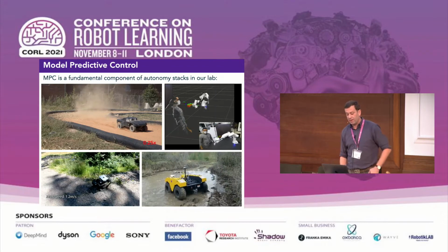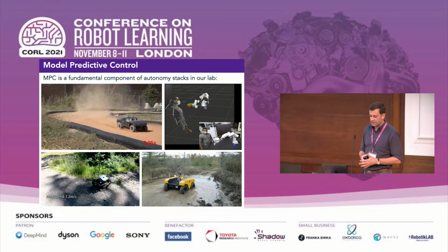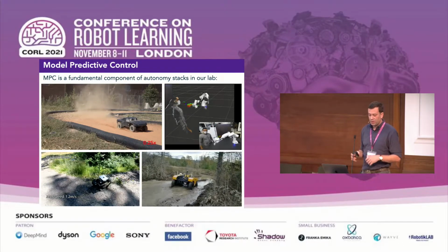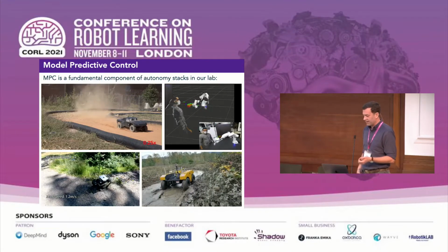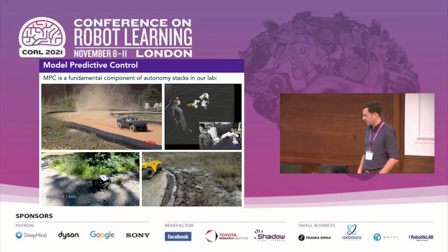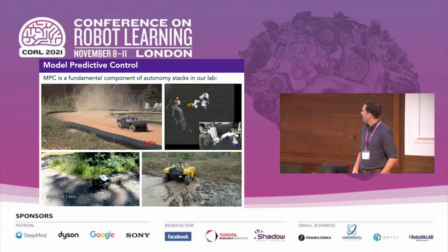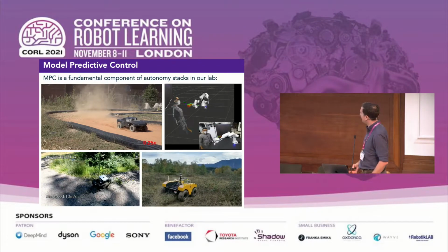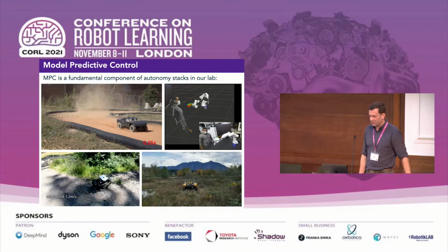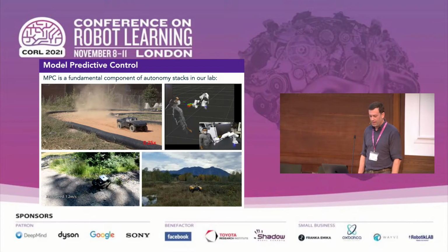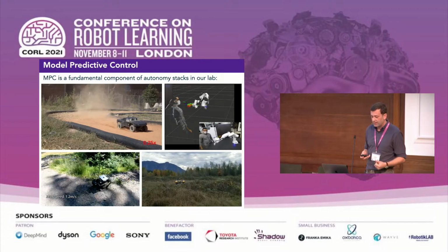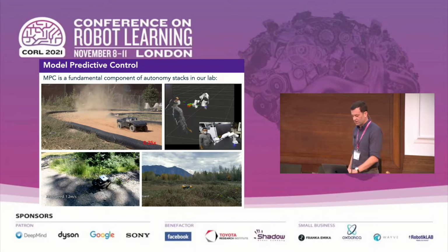And then finally, we've been using MPC for the control of larger ground vehicles as well, like this skid steer ClearPath Warthog, to robustly traverse wet and muddy terrain and things like compliant vegetation while autonomously avoiding obstacles and staying near a global plan to GPS waypoints. As you can tell, it's been raining a lot in Seattle recently, so everything is soaking wet, but that means there's lots of slip and cool stuff for the robot to deal with. This has allowed us to use a single strategy that works really well in a wide variety of terrain, including things like dense forests and ice and snow.